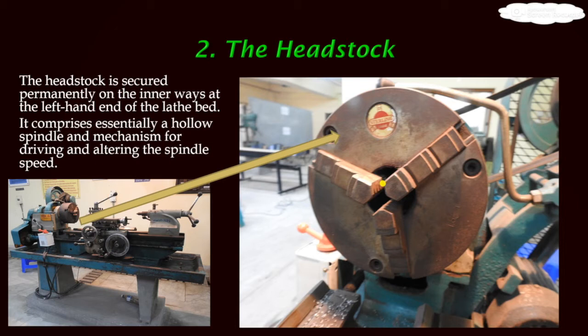So that is the facility. But if the surface of the workpiece is not regular, cylindrical, in that case we can't use this three jaw chuck. Then a four jaw chuck and other holding devices are there to hold that.